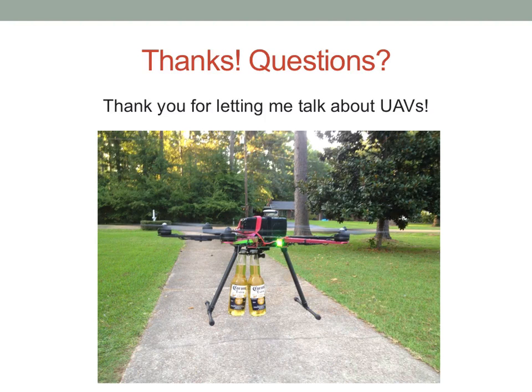What's your vertical limitation? Physically or by the FAA? Right. So physically, you're going to be limited by your remote control range, right? Once you get out of communication range to the drone, they have fail-safes in there where they'll stop and then fly back to where they took off. And so your line of sight range is a mile and a half, around there.